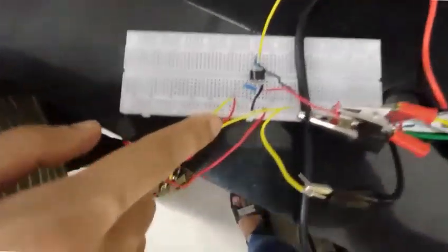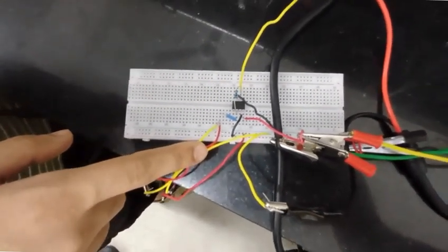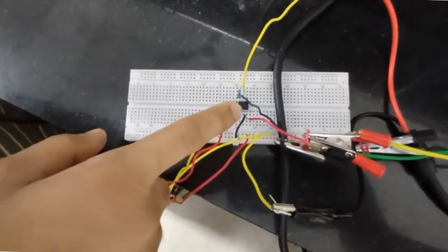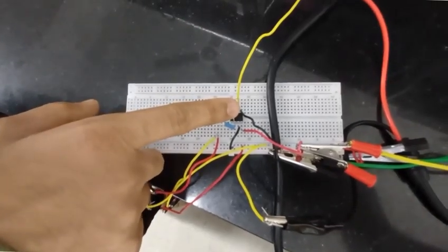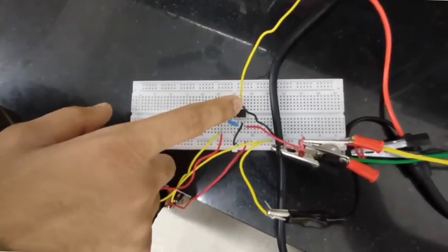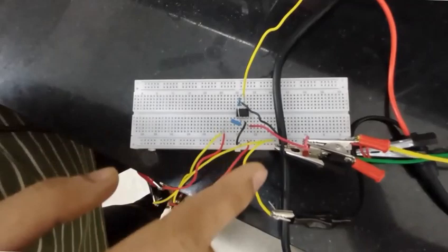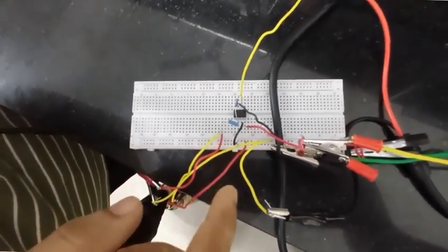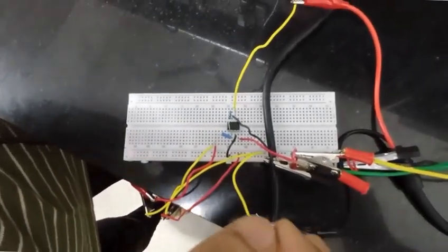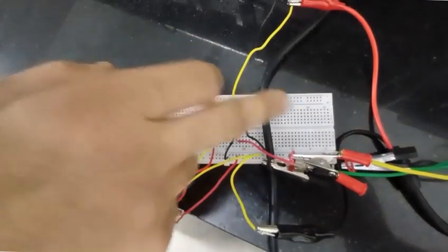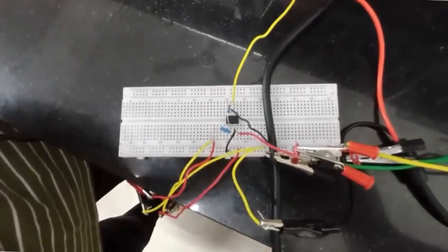This is the input wire which we have taken from the signal generator, 1 volt, 2 kilohertz, and this is the 100 nanofarad capacitor connected in series with the input. This is the 1 ohm resistor connected from the output to the inverting terminal, and the non-inverting terminal is here. It is grounded, and we have taken wires from the input and also from the output to the DSO to observe the output and input. Here is plus VCC, plus 12 volts, and here is minus VCC, minus 12 volts, taken as power supply, and here is the common ground taken from the power supply.